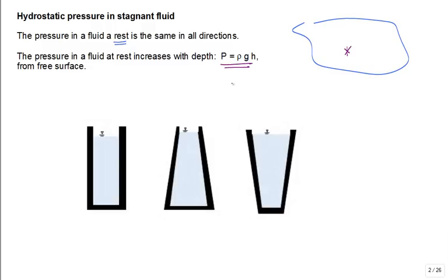How do we derive that equation? Do a free body diagram of a little column of fluid going down. Let's just go down from this surface down to a depth h. A very thin little column. Do a hydrostatic force balance, right? You have the weight going down. You have the pressure on that little area acting upward, the pressure on that area acting downward. Often that's the atmospheric pressure multiplied by that area. Let the area be very small, or we're going to cancel it in a minute.